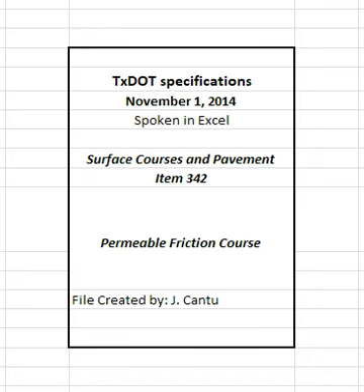4.4.2.1.15 Development of JMF2. Evaluate the trial batch test results, determine the target mixture proportions, and submit as JMF2 after the engineer grants full approval of JMF1 based on results from the trial batch. Verify that JMF2 meets the mixture requirements in Table 2. 4.4.2.1.16 Mixture production. Use JMF2 to produce Lot 1 after receiving approval for JMF2.